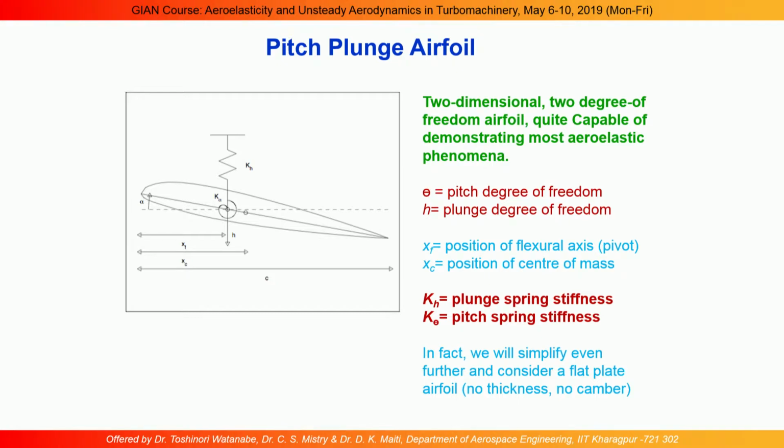As I am in the static analysis, I am solving only the torsional problem, so I do not need the bending equation. But in the dynamic situation, I need to consider both the bending deformation, which we call the plunge mode, and the rotational mode, the pitch mode. Pitch is the rotational mode about the y axis, and plunge is the vertical deformation.